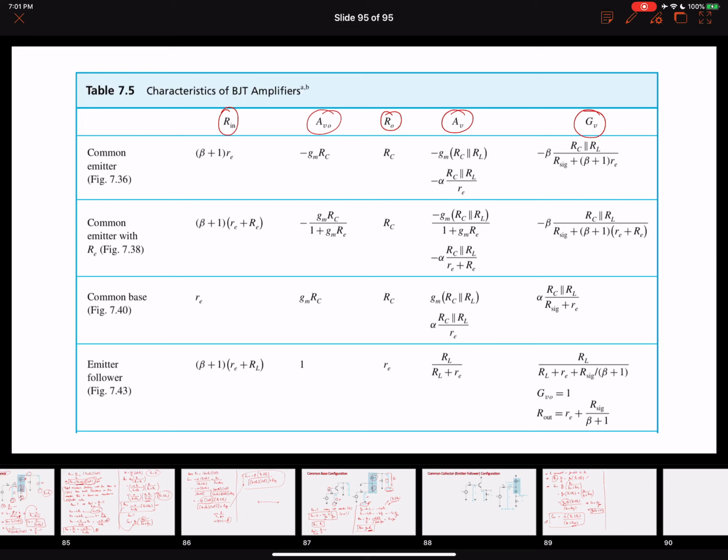when you will move to the next courses like digital electronics or physical electronics. Some of these fundamentals will be very important in order to design these microprocessor circuits, memory units. We very briefly touched upon how we can use a switch, the fundamental thing in any microprocessor unit. So we discussed very briefly how we can use a MOSFET as a switch or a BJT as a switch. A BJT as a switch can be used between saturation and cutoff. And in a MOSFET, we can use this in the cutoff and triode region.